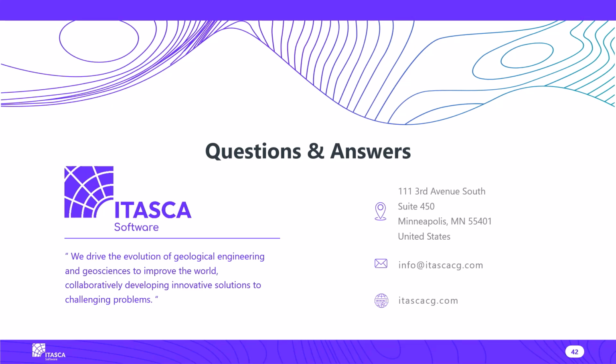But even though I said that, as it was mentioned during the presentation, what is critical to assess the amount of damage is how fast it goes from peak to post-peak, and that has to do with how brittle or how ductile the rock mass is going to behave. So with this relationship, where with this amount of plastic deformation you are going to end up with this first residual, that is the key parameter for the calibration. If you make it too brittle, then it will just fail almost immediately with little deformation. It will get to lowest strength. If you make it too ductile, then it's loading, but still it's not causing enough deformation. The degradation of the rock mass is not so fast. And that is the parameter that was used for the calibration, this critical strain.